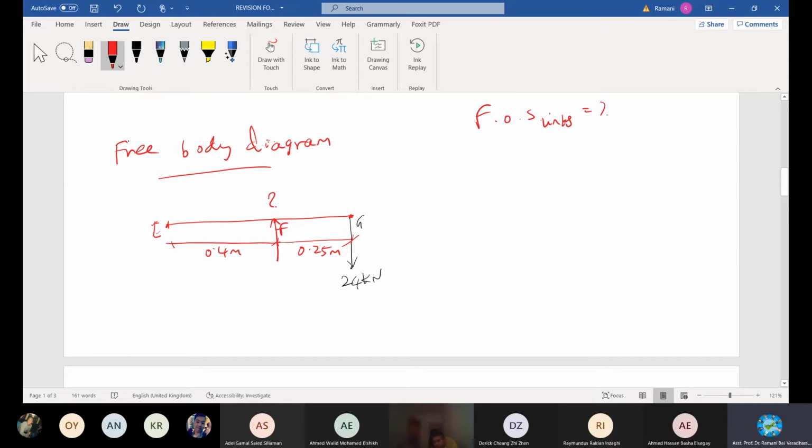How do you find the force? We can resolve the force above E, right? This is the pin. To find the unknown, either you take G or E, but I want to know how much is the reaction at this point, so I need to make use of the loading. Let's take the point E. Resolve the moment about section E. By equilibrium conditions, the moment at E should be equal to 0 because of the pin joint. Taking this criterion, let's resolve all the moments about E.